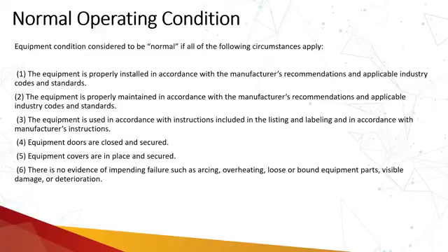So some insulation failures have started, but they are not severe enough to cause a flashover, or the maximum amount of fault current to pass. The failure is there, but it might not be that visible, or it has not reached the point where it moves from the potential failure towards the functional failure.